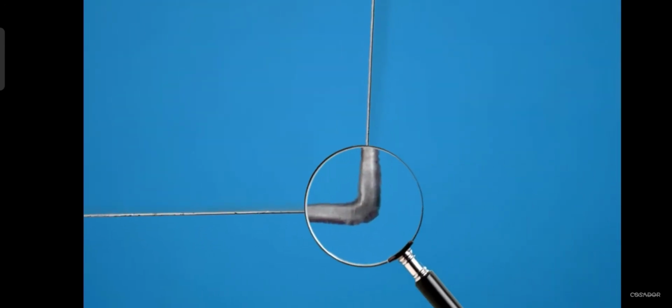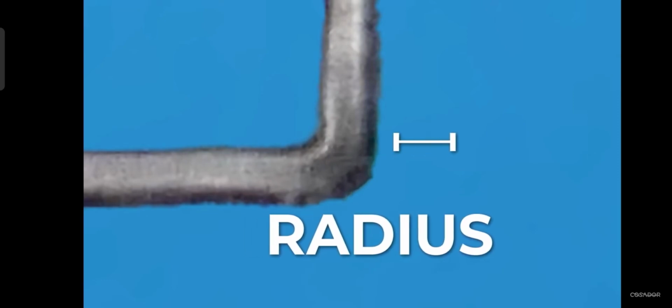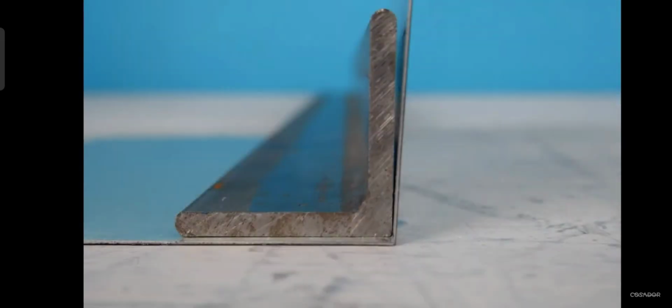In order to make a bend that's as tight and sharp as possible, I need to look at the radius of the bend. The bend is always rounded, and the radius is the determining factor of how tight or sharp the bend is. And the radius of the bend highly depends on the clamping material. Timber is not hard enough to make a tight bend, and I require something harder, like steel.